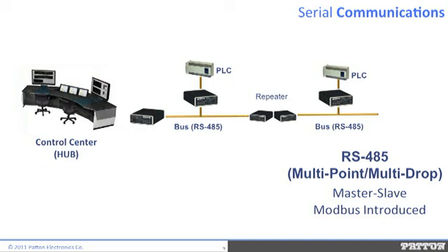It can operate over 2-wire or 4-wire. Simplex, though rarely, half duplex, the most common, and full duplex in 4-wire mode only. The data rates can reach up to 35 megabits per second, and as with current loop and RS-422, the twisted pair offers high immunity to electrically noisy environments that may have motors, welding equipment, etc.